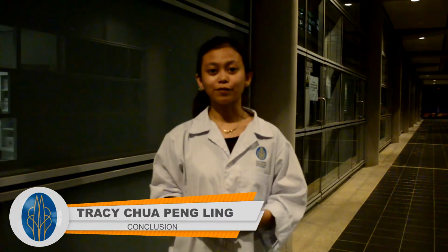In conclusion, we are able to study the effect of the initial height, the concentration of the solution, as well as the volume of the flocculant towards settling rate. We are able to conclude that the lower the initial height, the shorter the distance between the solid particles and the lower end of the cylinder. With the short distance, the traveling period of the solid particles down towards the bottom of the cylinder is shorter.